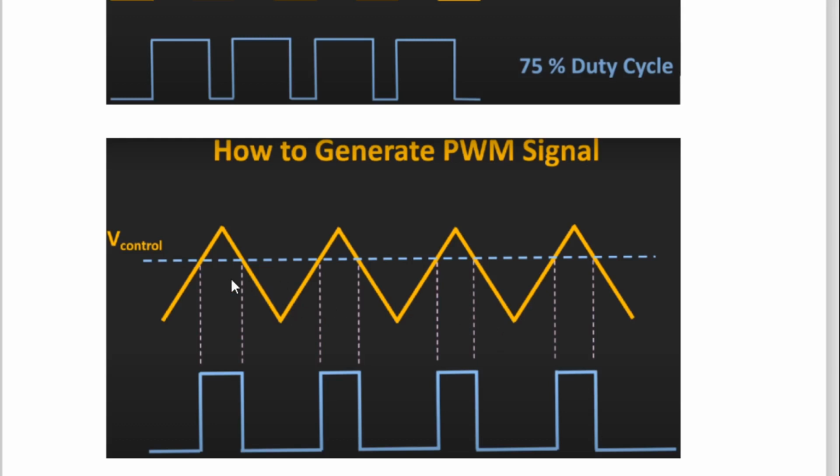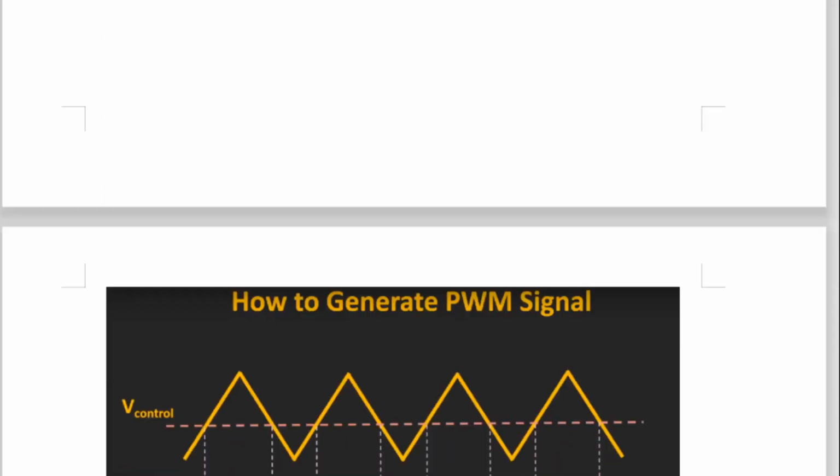Here they have taken it in inverted form. When the triangular wave is above the sine wave, they have given it as HVL, and this is the reference voltage. So when the sine wave voltage is greater than the triangular wave, the triangular wave is below the reference voltage, so it is taken as LVL. You can apply it in inverted form, there is no problem.